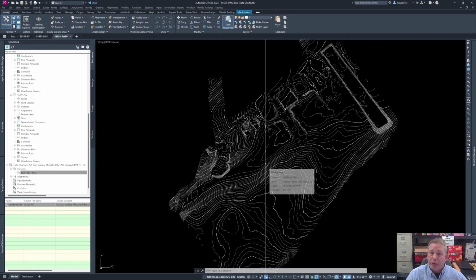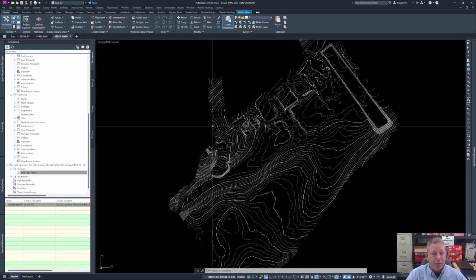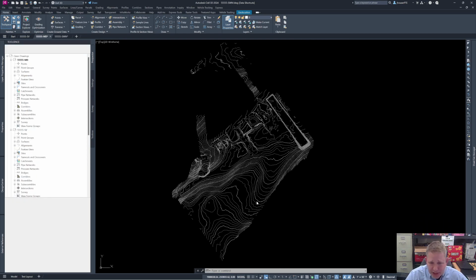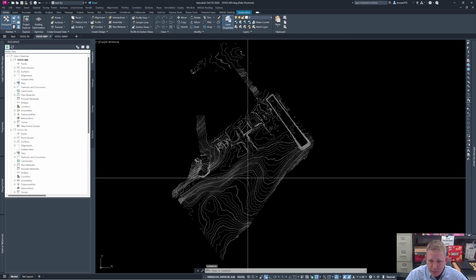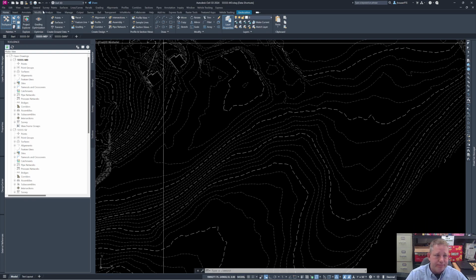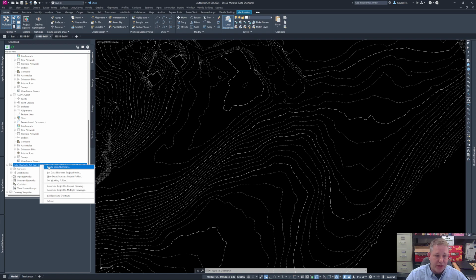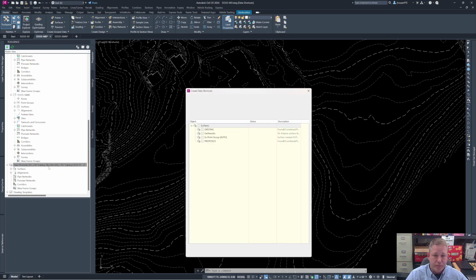So for the stormwater, they may be data referencing the existing surface and a proposed surface. I was really hoping to have a proposed surface created already. Let me do something real quick here. Let me see, do I have a surface? I have a proposed surface here, so that's good. What I can do is, in this case, I can go down to the bottom. I would right click on that and I would say create data shortcuts.